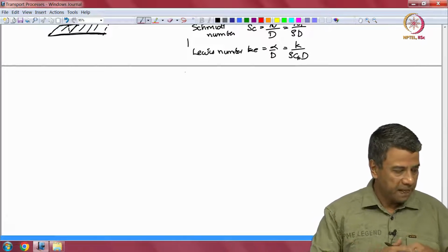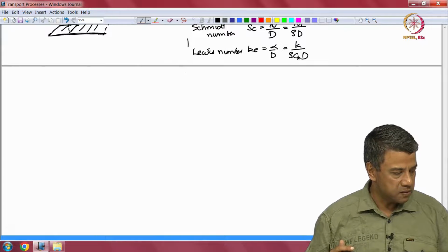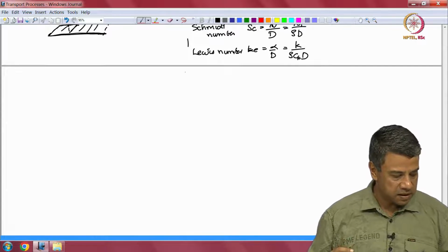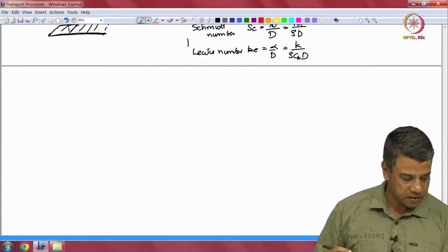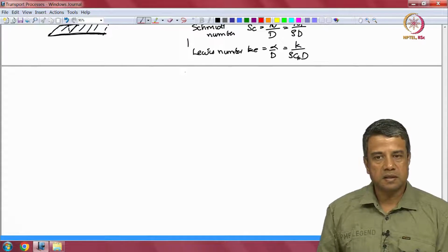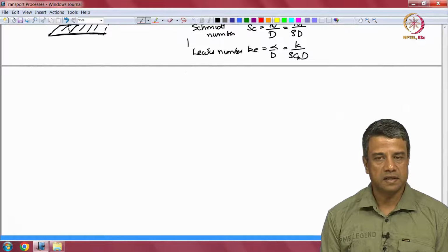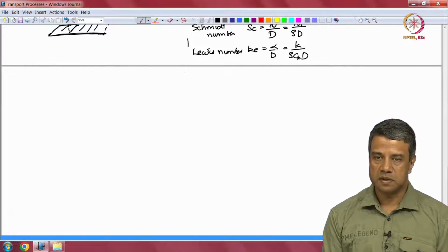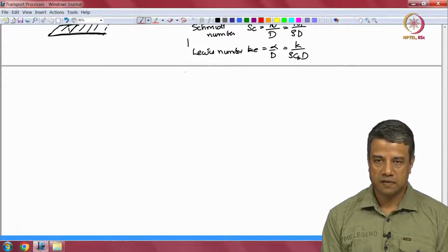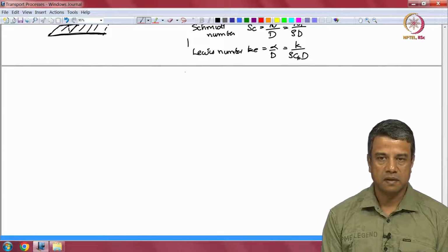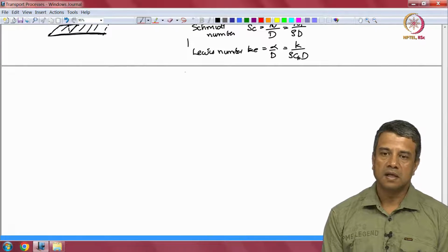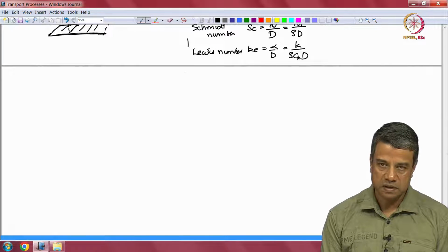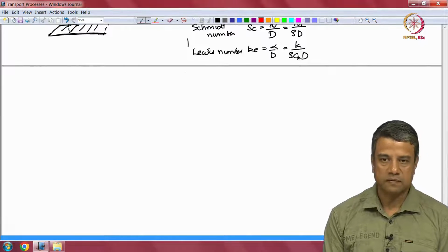Okay. There are other dimensionless groups also which are sometimes of interest. I will just go through some of these. So the independent dimensionless groups are either the ratio of convection and diffusion or the ratio of diffusivities, and the dependent dimensionless groups that we want to determine are the dimensionless fluxes, the dimensionless average mass or heat flux for mass and heat transfer, and the dimensionless average momentum flux, the friction factor, the drag coefficient, etc., for momentum transfer.